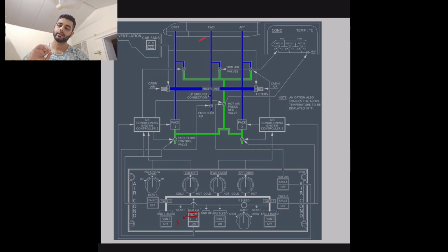So I've landed the aircraft, my speed has come to 70 knots, now a 20 second timer starts. After 20 seconds, the ram air inlet flap will open. Hopefully you slow down by then. Otherwise, 20 seconds at 70 knots, do the math, see how much runway you have.